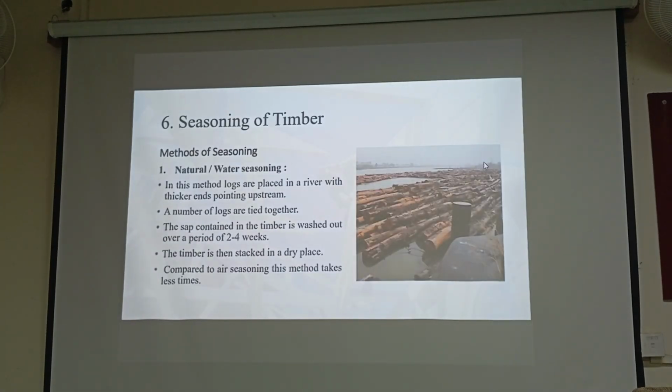Then there is water seasoning, where the logs of wood are kept in the rivers, where the wood will stay for 2 to 4 weeks, and this will remove their moisture. This is also a natural process of seasoning. It is a better process, because there will be a low amount of shrinkage or warping of the tree, as it will remain in the same position and same surface, so it will have better seasoning capacity.